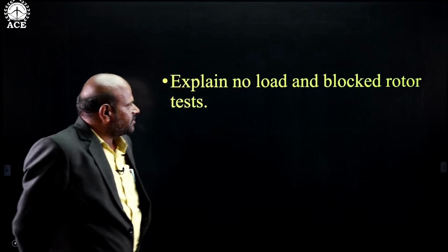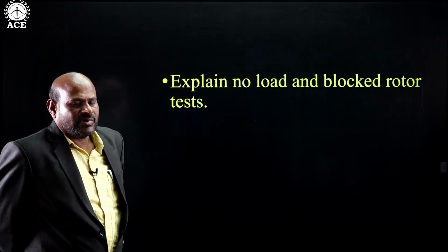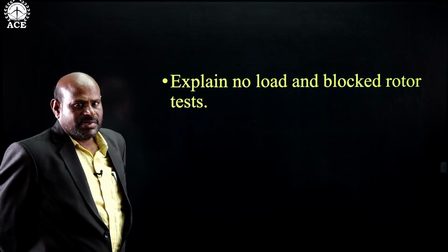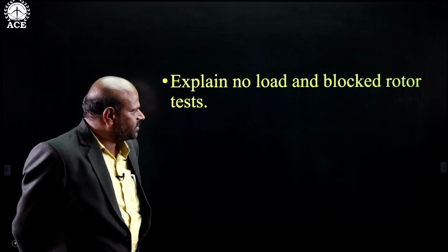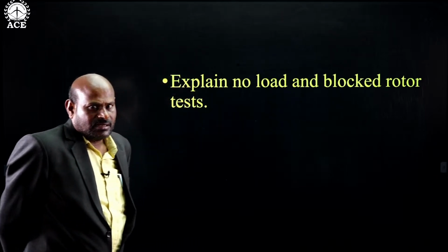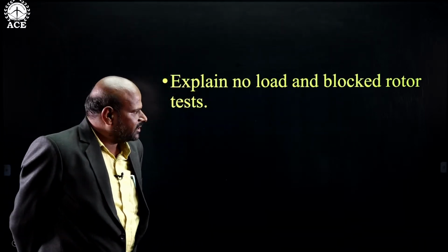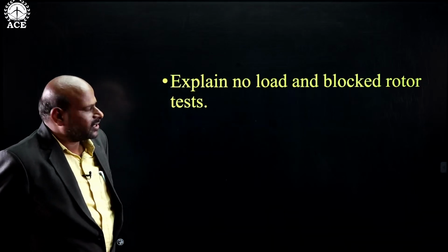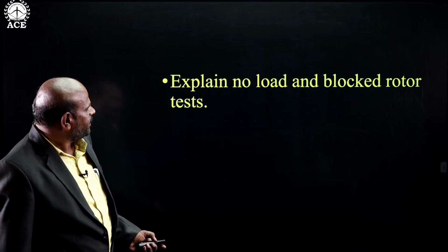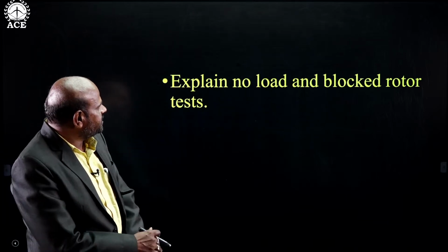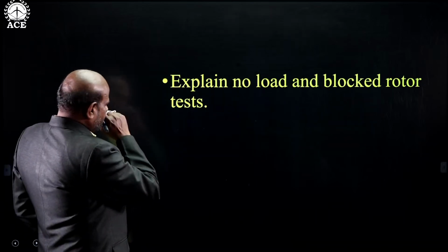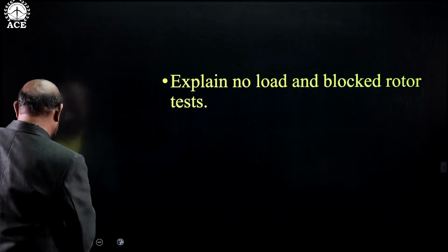For that, you have to draw the performance characteristics: torque, speed, slip, torque versus slip, torque versus speed. You also need the losses in the machine under heating condition and running condition, and the efficiency. So mainly, for a three-phase induction motor, the tests performed are of three types.